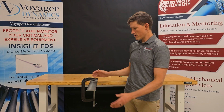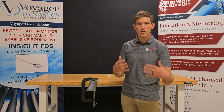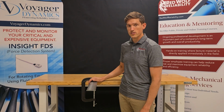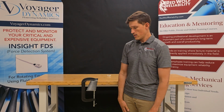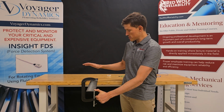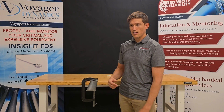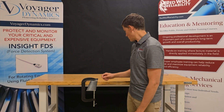Hey everyone, so here we have a cantilever beam demonstration. From the first slide in this video, I talked about how strain will develop in this cantilever beam at the fixed end. You should see the highest strain at the fixed end, with little to no strain at the free end. That's because when you bend this beam, you have a moment that's resisted only at this fixed end. So we're going to try and demonstrate that with collection of dynamic strain data, and then we're going to also show a comparison of what acceleration data might look like on this beam.